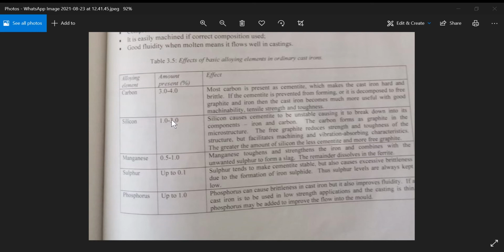So this means they act as stress concentrations at the tips of the flakes, and under a tensile load, cracks can develop. This is why grey cast iron has good compressive strength yet poor tensile strength. To improve the tensile strength, there are cast irons where the graphite forms into a rounded clump instead of a flake. So let me explain that a bit more.